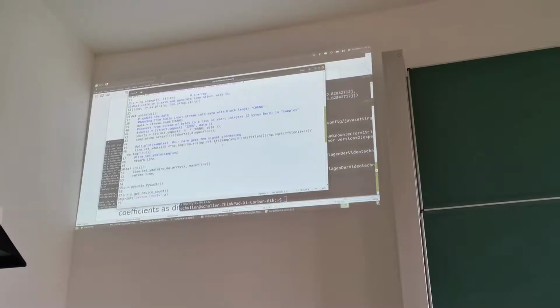Here I'm then computing the FFT. You can see FFT of the samples of the size of FFT length. Here I do some normalization, which is not really important. Here I'm taking the magnitude of it. So this is actually doing the squares of real and imaginary part and the square root. And then I turn it into a dB value here, 20 times log.